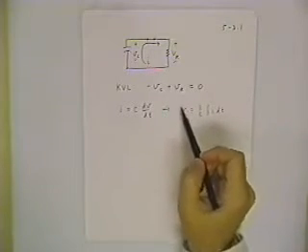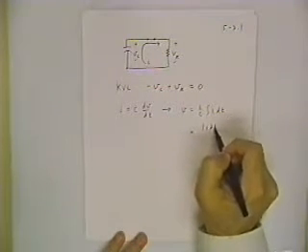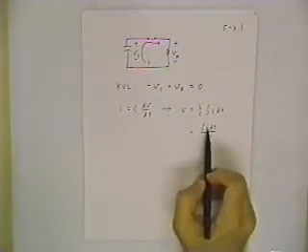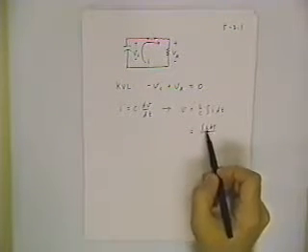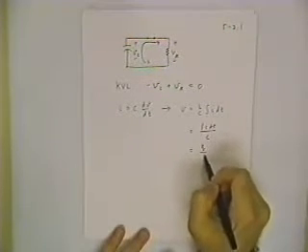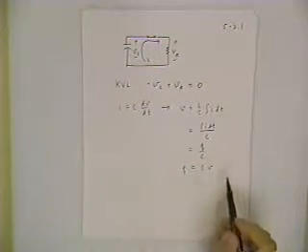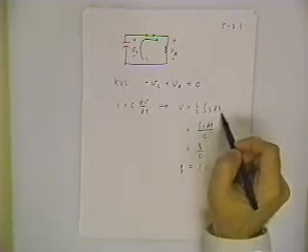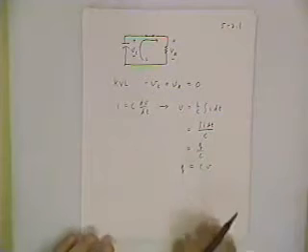And you've actually seen this equation before. If you just look at what is the result of integrating a current over a period of time, well, you can find out the answer just looking at the dimensions. Current is in coulombs per second, dt is in seconds, and so if you cancel out the seconds, you get coulombs. And so what we're actually looking at is charge over capacitance, and this is our familiar Q is equal to CV. So again, this might be a way of remembering this form of the model for the capacitor. This is the equation that we want to use now to substitute for V sub C.